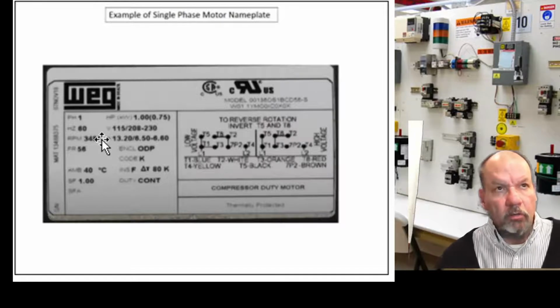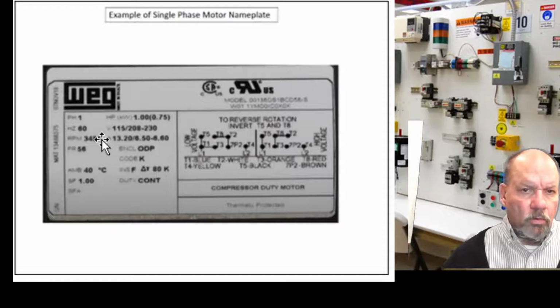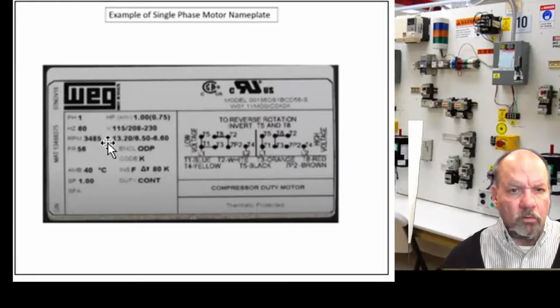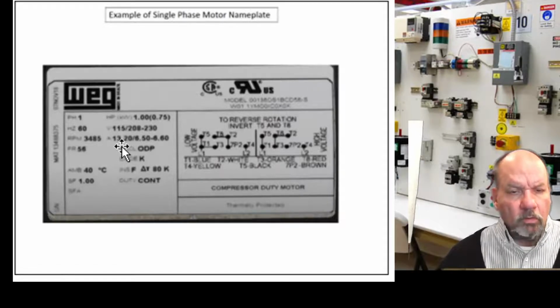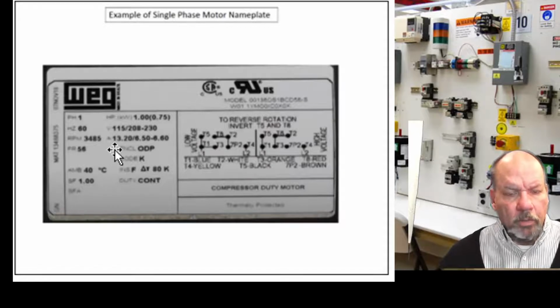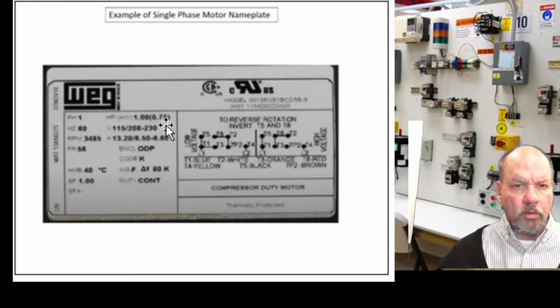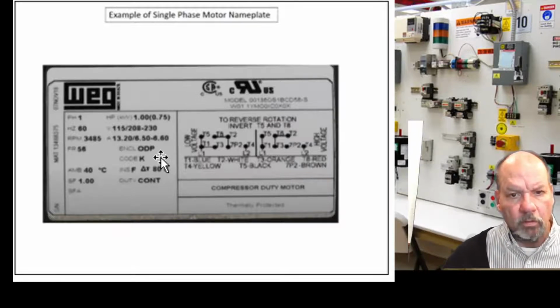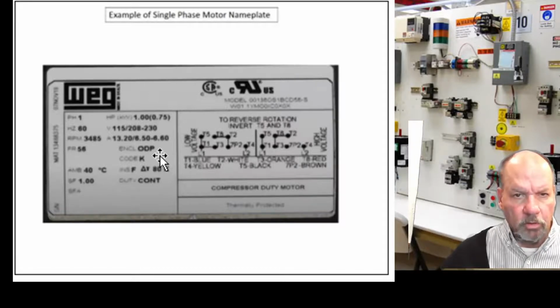Now, since power is equal to voltage times current, if we work at a low voltage, 115 volts, which is shown here, that's considered low voltage. We're going to be operating at 13.82 amps. That develops 1 horsepower. Now, if we take that to high voltage, basically double the voltage, then the current has to go in half. So the current at 230 volts would only be 6.6 amps.